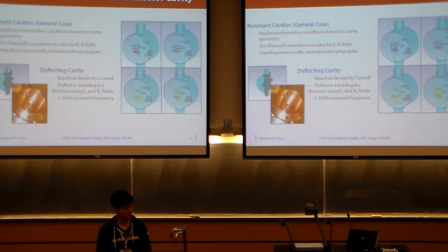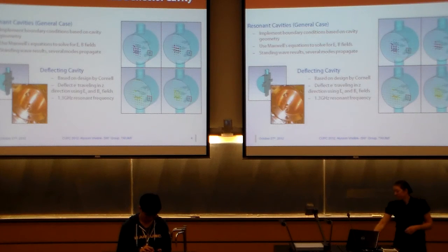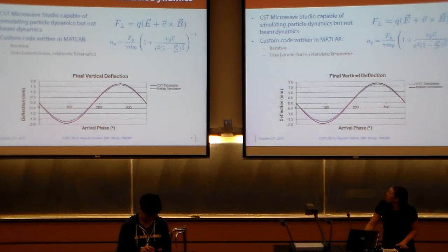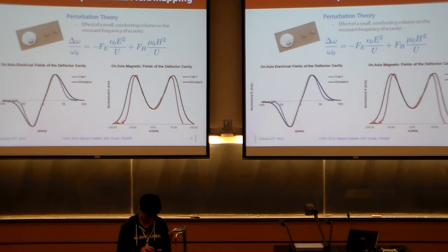And then you have to trim these nose cones to get to the proper frequency, so get to 1.2 gigahertz. But now the nose cones have changed compared to what we saw in our simulation. So what that actually does is it will change your field a little bit, and it will change the point at which they really come into effect. And that's what's giving us these narrower electric and magnetic fields, because we've done some trimming of those cones.